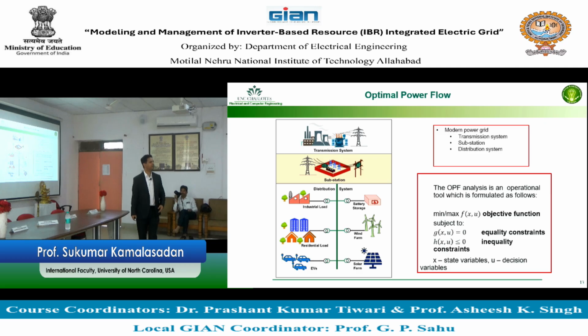What happens if this PV farm power is not a fixed number? It's going up and down. So the PV power can be plus or minus, right? Let's assume that it is a net load. You remember the net load we talked about. What is a net load? PV plus load. If the load is higher than the PV, it is positive. If the PV is higher than the load, it is negative, depending upon the sign convention. Positive means absorption and negative means you're pushing. So this can be positive or negative.